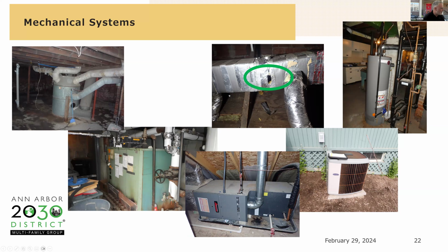This picture at the bottom in the middle, if you have furnaces or ductwork, same with the picture on the top, that are in unconditioned attics, do what you can to get that into conditioned space. That's going to go a long way towards reducing your energy use. You have to overcome all the cold or the heat that the duct system has built up in it when this thing starts up. And then here's this picture in the top middle here.